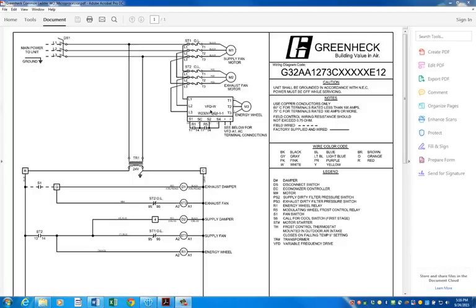This is a variable frequency drive used to power this energy wheel. So L1, L2, L3 go in, T1, T2, T3 go out to a motor. And there's various signal lines that go to this drive. But the key thing is the correlation between the symbols on top here, ST2 and ST2 here. So you could really look at this as the power circuit, the high power circuit, which is controlled by the low power circuit.